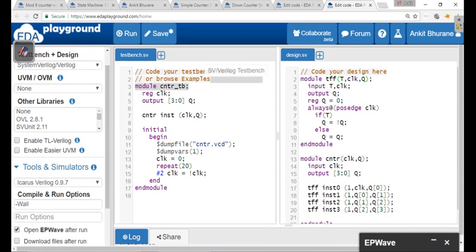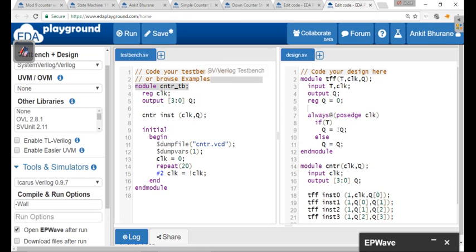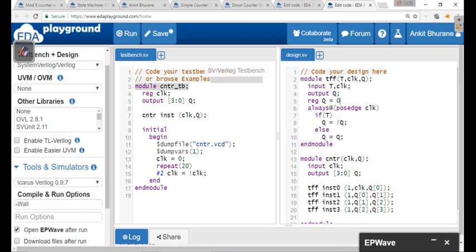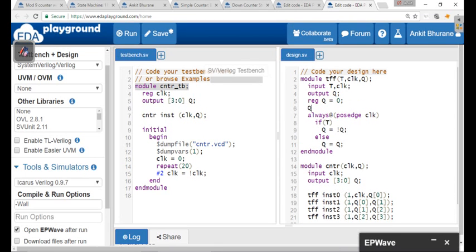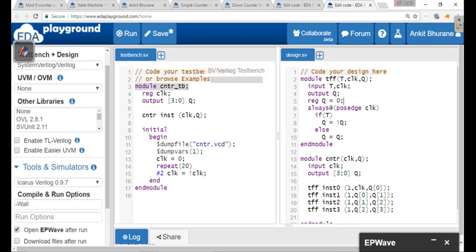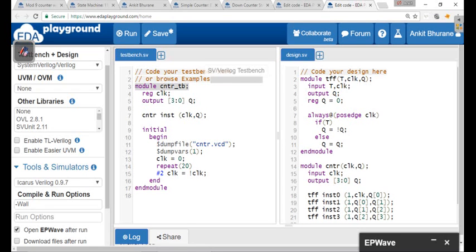So let me say assign. You can specify this QB as the complement of Q here itself, but not directly. You will have to specify that with assign statements. If you do that, then you will get the output. It is incrementing properly, but the initial states won't come there. So I am just not modifying this. So this is now the down counter. Get such kind of output.